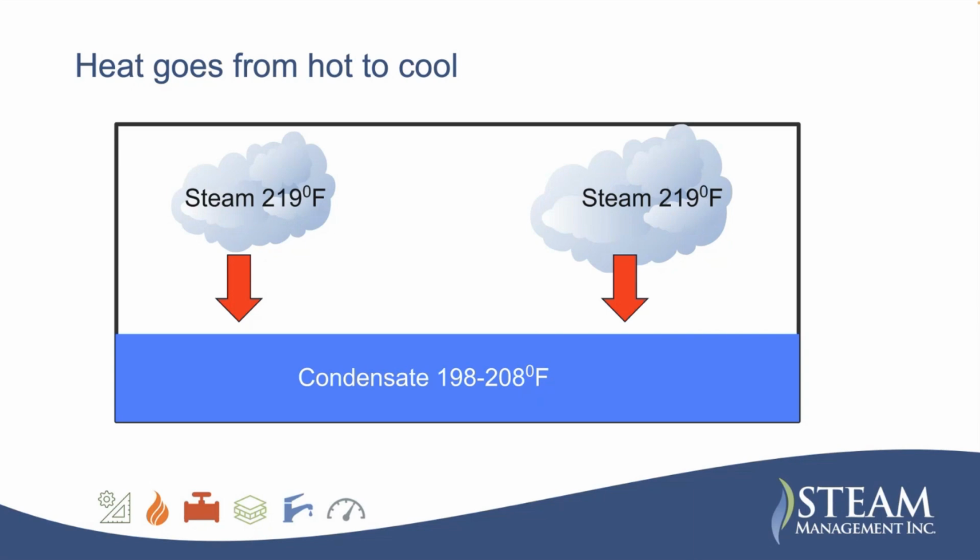Yeah, I think so. A lot of people on the call, I'm sure, are familiar with heating degree days and cooling degree days, but that's how I would typically approach it as well. Just look up the heating degree days for that region, and those vary year by year. When we implement efficiency projects, we go back, look at fuel bills, and establish a baseline. Then for the new year, it may be a colder or warmer year, so you use an adjusted baseline to compare savings. Thanks, Ray.